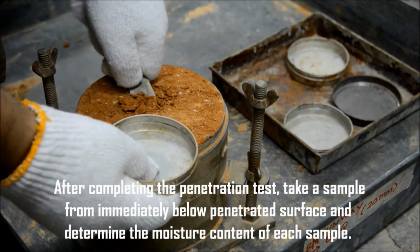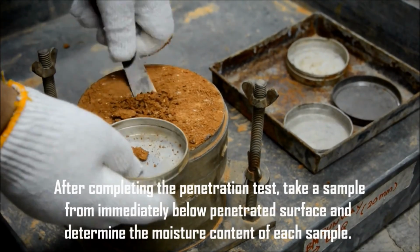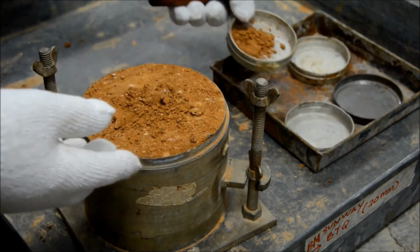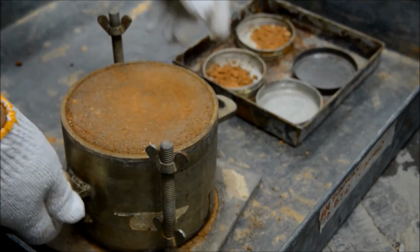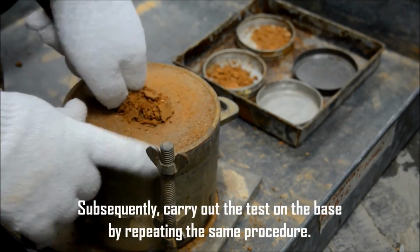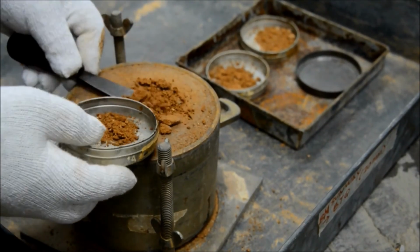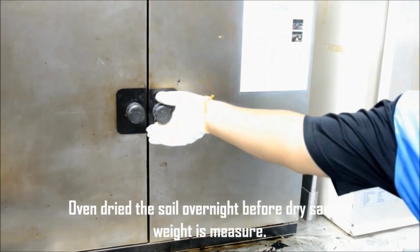After completing the penetration test, take a sample from immediately below the penetrated surface, and determine the moisture content of each sample. Subsequently, carry out the test on the base, by repeating the same procedure. Oven dry the soil overnight, before the dry sample weight is measured.